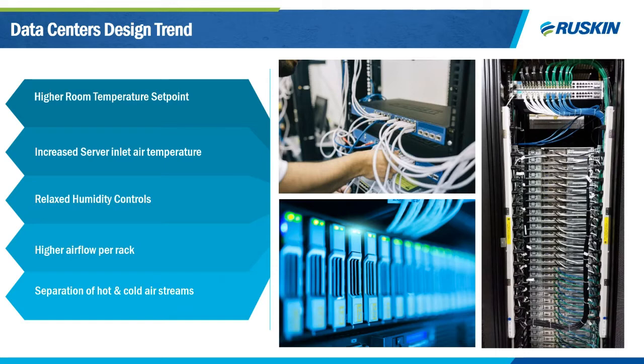But it also opens the door for other strategies or opportunities that perhaps may not be attainable when your set point was 55 degrees supply air temperature. Now we're bumping this higher, so we could use more opportunities. And so we'll talk about 100% outside air economizer and the opportunity for it.